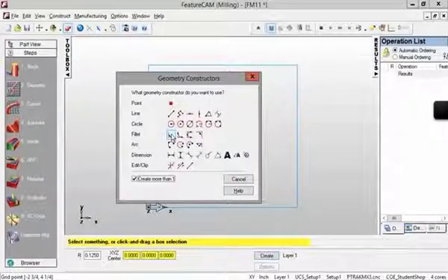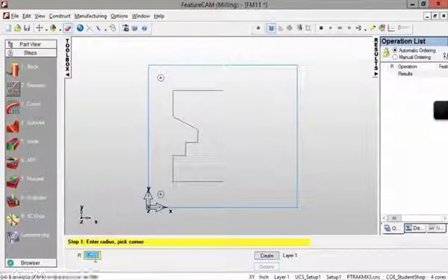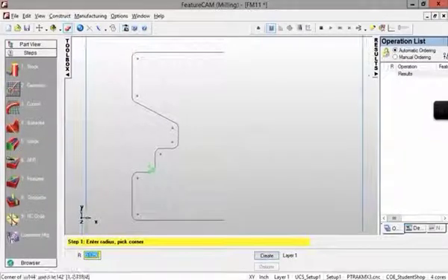For the fillet option, there are 4 different ways, but here we want to use the simplest one, the corner fillet. Once you define the radius of this fillet arc and you select the corner, it will help you draw out the fillet automatically. So we want to put in our radius as 0.125, and then click here. See, it's done, right? Pretty easy, and do this for all the sharp corners. If you zoom in, you can see it's never sharp again.